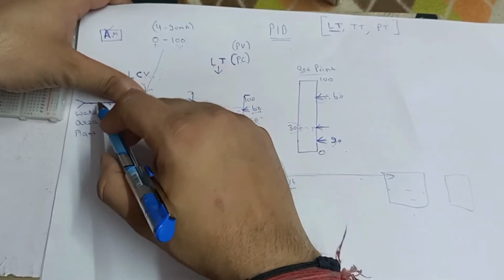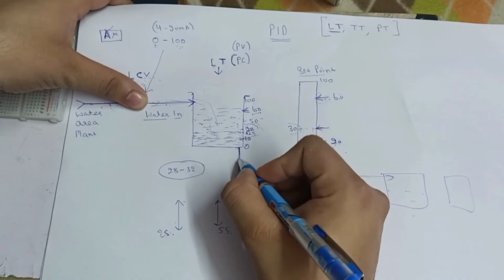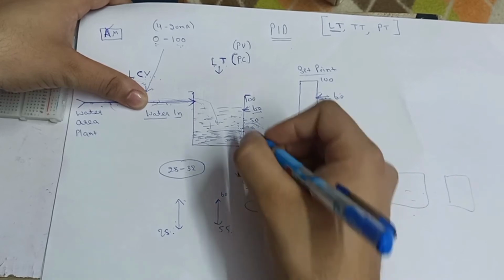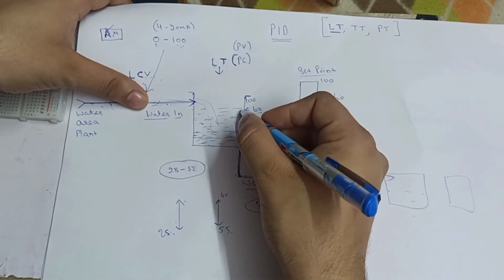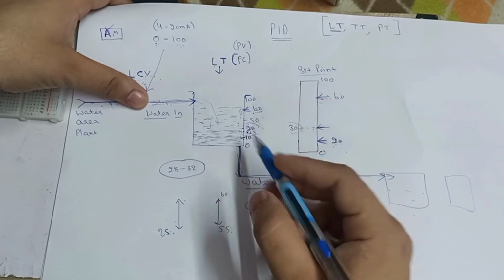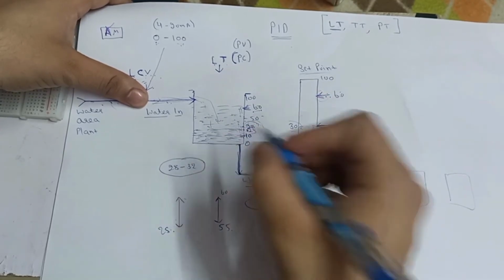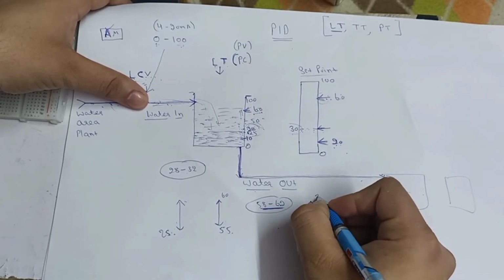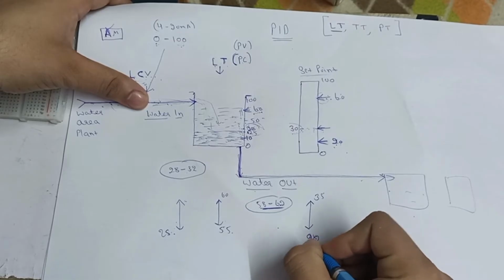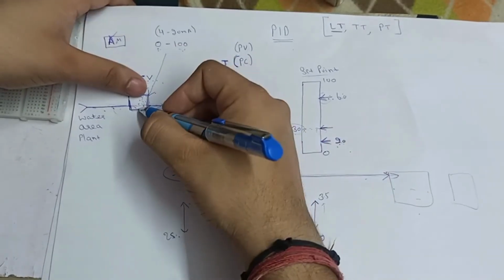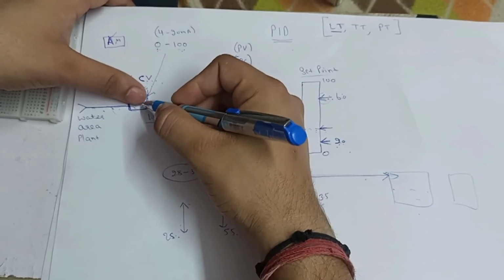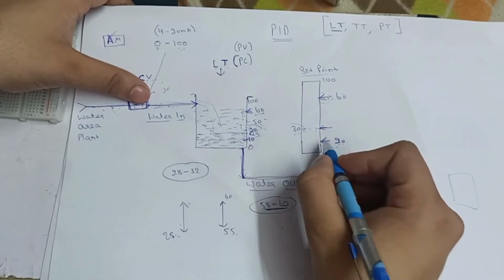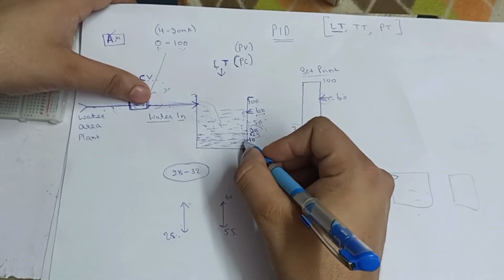Because the inlet is here and it tries to decrease, the water level decreases here. After a few seconds, the water decreases very slowly, like 60 to 50, 40, 30, 35. Then, taking another example, after 35 to 20, the LCV starts to open very little, like 20 to 30%, because we need to maintain 20, not very low.